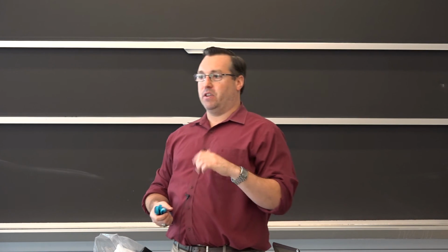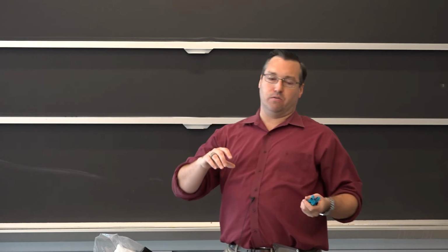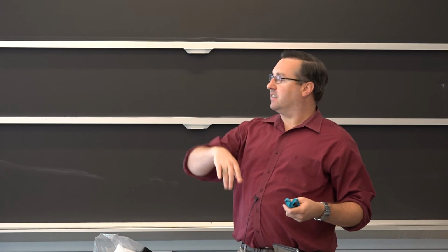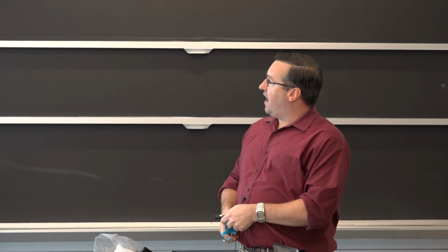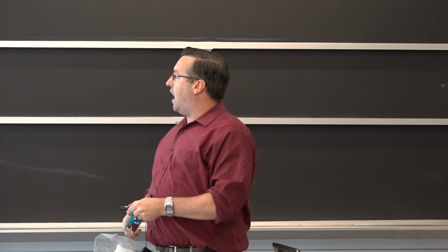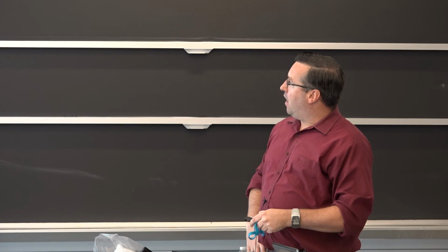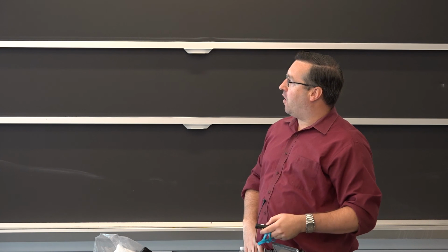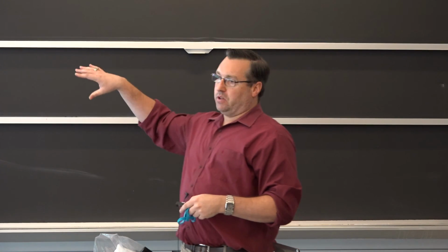So you need to make sure of the properties when you need to do some testing, and you can do similar tests on plastics. That can be done. They actually have a different scale. Plastics operate off of a Shore scale, a different hardness scale, and it has different values. But you can also do this for plastics.